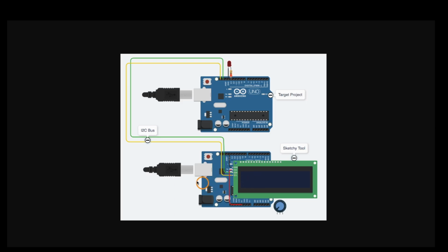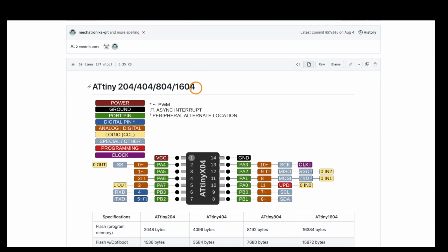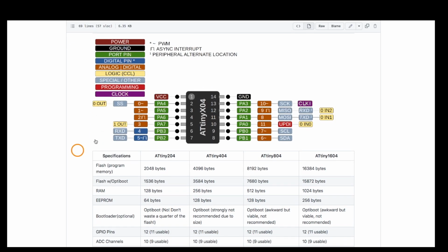And now, looking at the sketch for this other setup, the schematic will be reviewed in the other video when I get this PCB made. But for now, just looking at it as some sort of processor with an OLED and a rotary encoder, if we look at that sketch in the Arduino IDE, I use the ATtiny core board file to get ATtiny 1604 support, and then these are basically the pins we would refer to within Arduino. So the dedicated hardware I2C pins are right here, and that's what I'm using to talk to that other Uno project to change the LED blink rate.